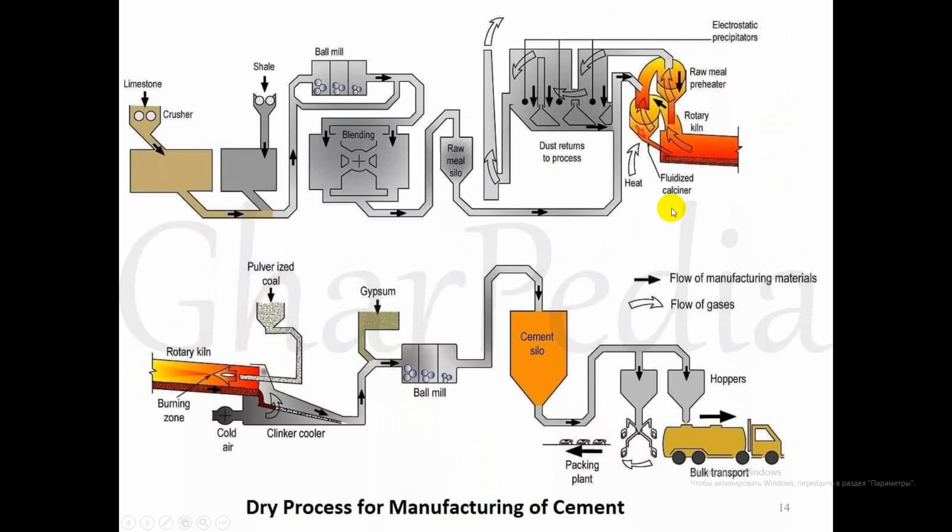The temperature in a cement kiln can reach 1400 to 1500 degrees Celsius. Slurry in it is heated and dried, and finally forms the clinker compounds, namely dicalcium silicate, tricalcium silicate, tricalcium aluminate and tetracalcium aluminoferrite.